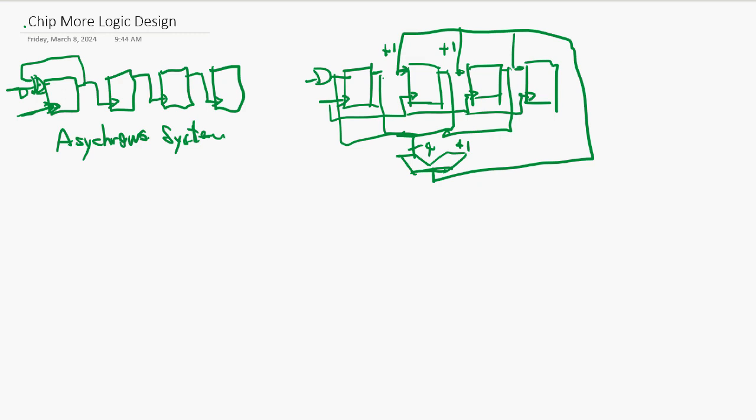And you may think, why do you need an adder for just a counter? Well, it's just a plus 1, so it's going to be simple logic like AND. Go there, and AND goes to the next one here. Basically data is registered every clock at the same time, and the data is incrementing one by one. This is synchronous.